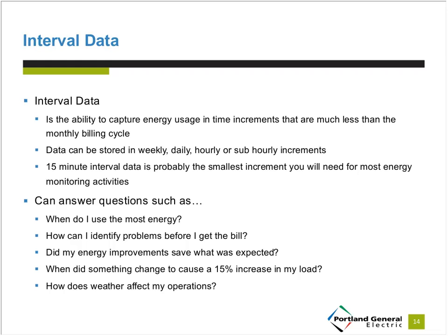If you have interval data, it can answer all kinds of questions for you. It can really answer, when do I use the most energy? And it's not what month, but it could tell you what hour of the day or what week or what day. It can also help you identify problems before you get a bill. If you're able to look at that data regularly on a daily basis, then if something all of a sudden shoots up, if some instrument or some machine turns on when it shouldn't, you'll be able to see that over a few days and make adjustments before it costs you a lot of money.